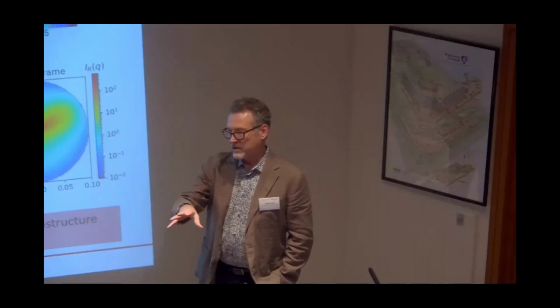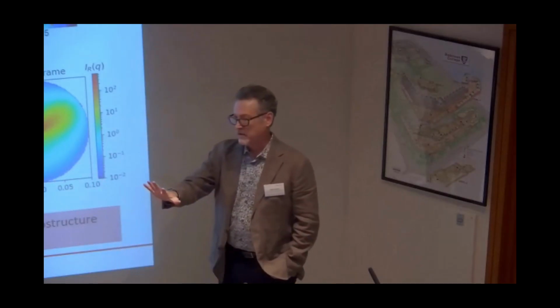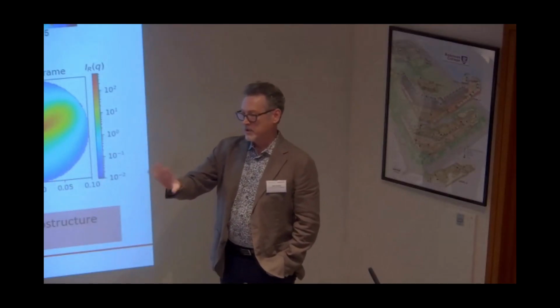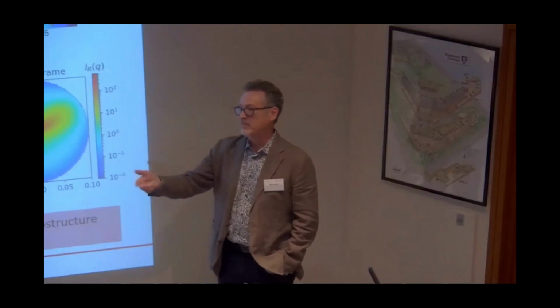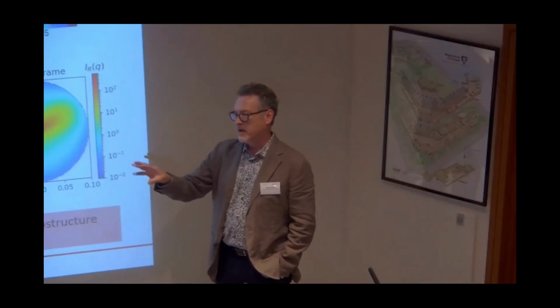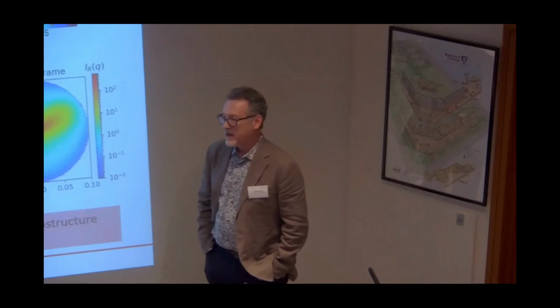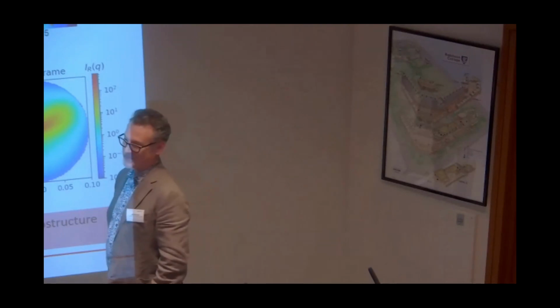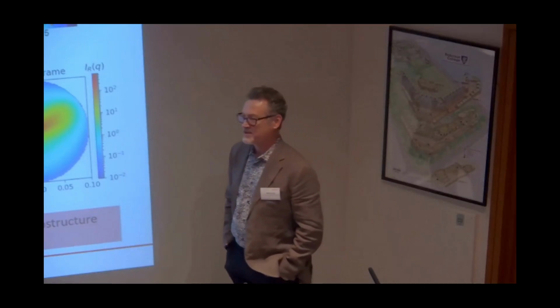What we think it should be possible to do is, if you also have microstructural data, determine a stress field that's consistent with the force density and consistent with the microstructural data. Those additional degrees of freedom would hopefully get rid of the degeneracy that you have just from the divergence operator. We think that should work, and that's where we're going with this.